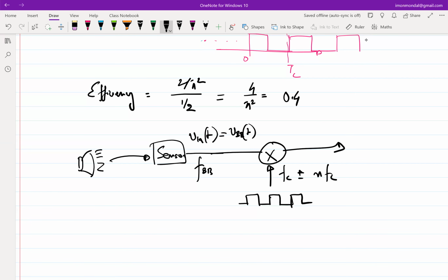Now, as it turns out, an antenna, again, I am not going to prove this, but if you have taken any RF course, you will know that the antenna can be designed to tune it for an impedance of the free space, which can be modeled in some way. Typically, that impedance is kept at 50 ohms, right? So for the purpose of this course, an antenna corresponds to a 50 ohm impedance, a grounded 50 ohm impedance. One side is ground. You cannot have access to the other terminal.